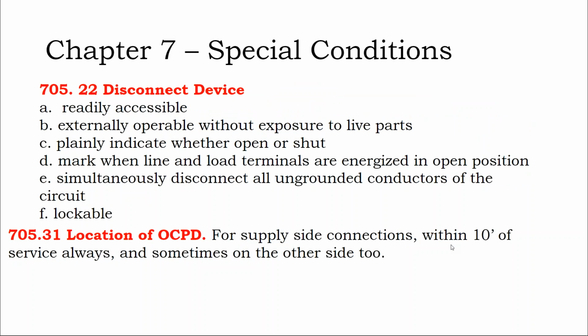We see the disconnect requirements are the same as the solar disconnect requirement. They have to plainly indicate whether it's open or shut. That doesn't have to be a knife switch, but you have to be able to look at the switch and see if it's open or shut. Lockable, simultaneous.